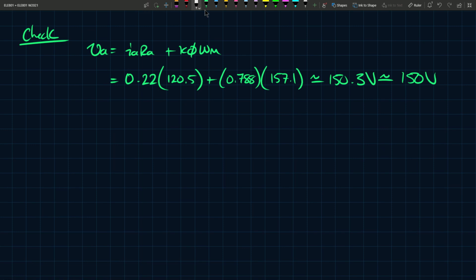And then we can say if Tm star is 85 Newton meters, we can move on to the second part. So we're transitioning from the first part into the second part. If you give a reference of 85 Newton meters, which is what they're asking, then this torque, I should say not rated, it's reference, star is a reference, will require some reference flux and will require some reference armature current. You can obviously calculate this based on the equations that we have.